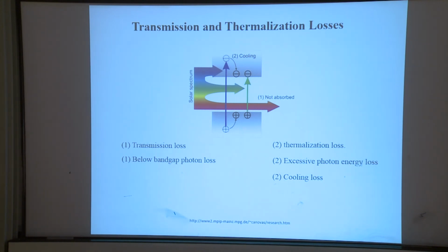If you have band gap that is suitable for green light absorption, then it will not absorb red light. So red light is passing through without being absorbed by your semiconductor solar cell. So it is wasted. And also, even though you choose a band gap corresponding to the green light, you cannot fully utilize the energy of blue light.